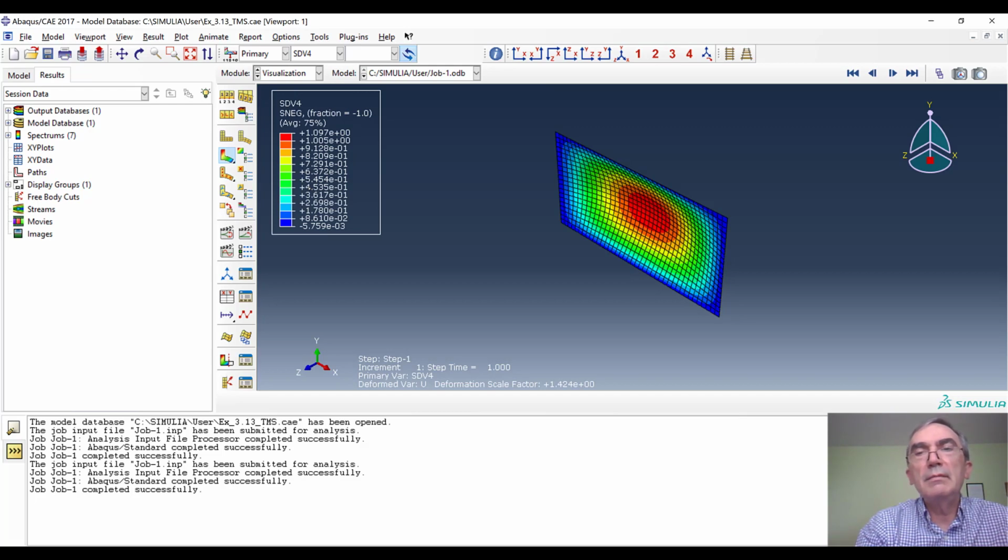When I look at the plot for the matrix, what I can see is this number is 1.097, so it's barely failing. It's starting to fail. When I see this number, I say the matrix is failing. And pretty much that's it. We got all the results from the truncated maximum strength display for us. This material model is not available in Abaqus, but you can write it, and now Abaqus can do this for you. Okay, thank you.